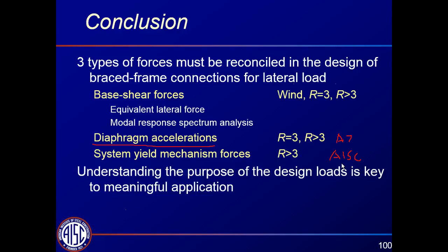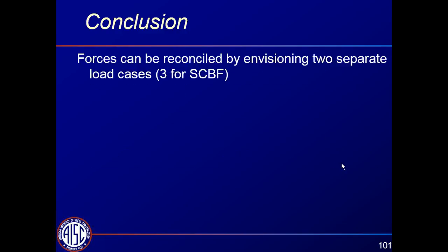Understanding the purpose of the design loads is, I think, key to applying them in a meaningful way. The forces can be reconciled by artificially creating two different load cases to derive design forces. One of those is based on the vertical distribution or the mechanism forces, and the other one puts in the F sub P force and then makes an adjustment.